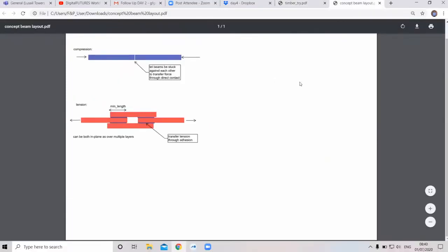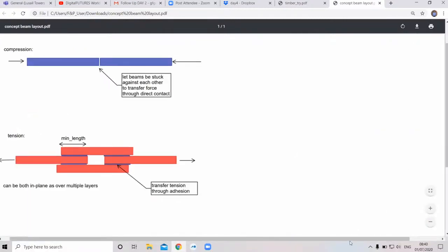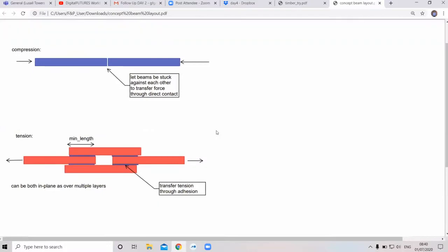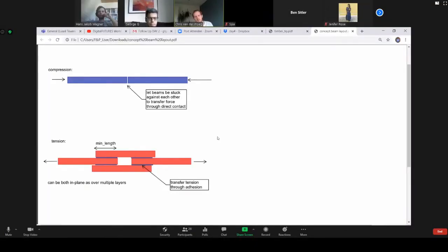Towards the slat pattern, I was thinking, in a beam you always have a compression side and a tensile side, which swap above the supports or in the middle of the span. And I think the slat pattern that is structurally efficient will be different for the compression side than for the tension side.